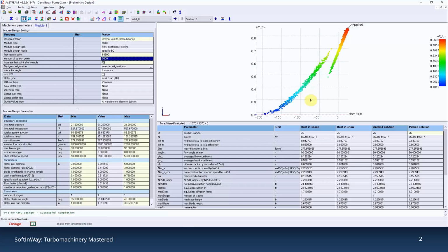Design candidates with a value lower than 0 here are going to be subjected to cavitation, so all of the ones here with the higher rotational speed. The ones over there are, however, going to be cavitation free at the design point, and the higher the value, the more cavitation resistance they're going to have. The idea of this module is for us to determine which of these designs or others we want to select for the detailed design process and the analysis.